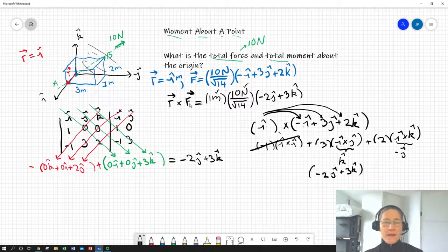So that is it. We have determined the moment about a point exerted by a force and applied our R cross F cross product in 3D and avoided a gnarly geometry problem. So that is it for this mini lecture, and enjoy calculating some moments about points.